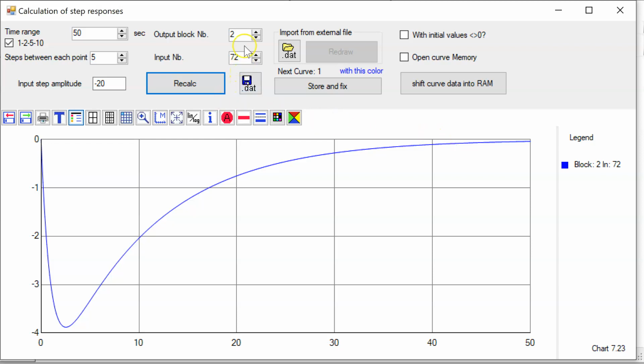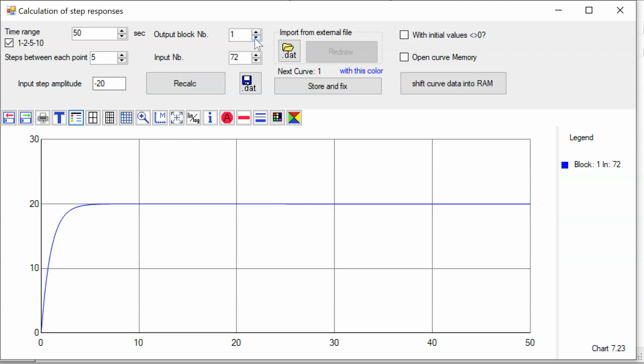We have to check the power signal. If you go up to the power, you see the motor power has no peak, it just must increase its starting value up to 20 kilowatts. That's to compensate the disturbance force, the disturbance power. So there is no motor limitation, no limitation that can influence our response in a negative way.